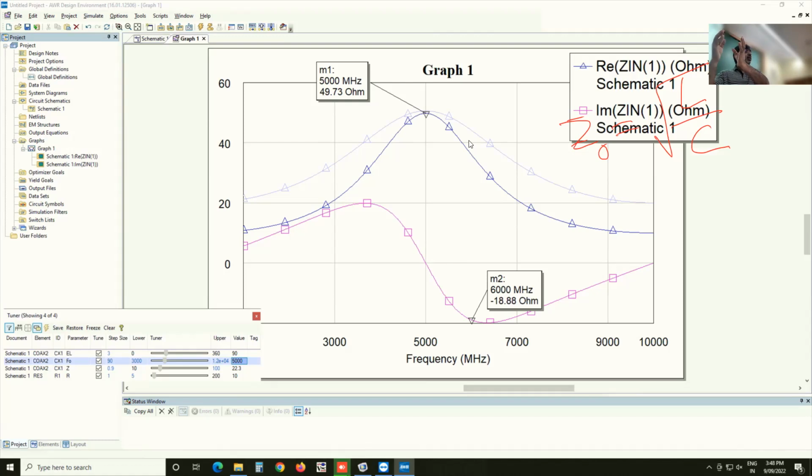It looked like a transmission line. As you go closer to 10 ohms, your transmission line impedance will be closer to 10 ohms. It will be slightly smaller. So remember, to match 20 ohms to 50 ohms, you needed a transmission line of 22.3 ohms.